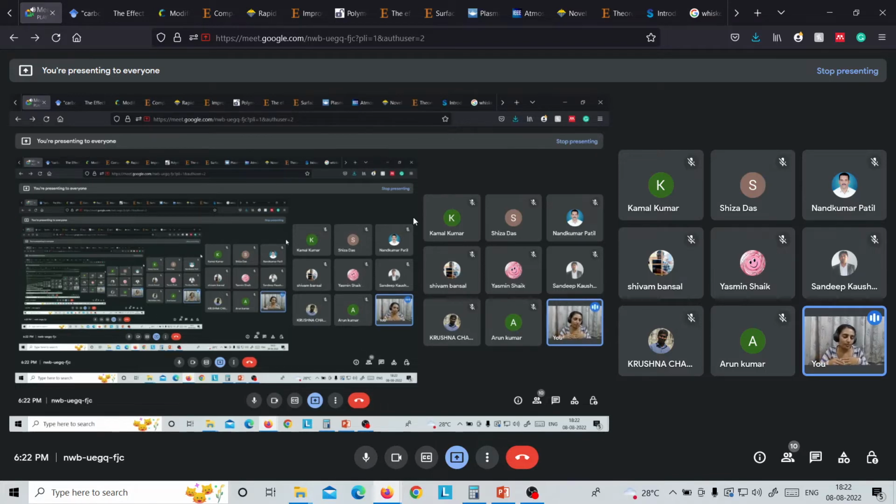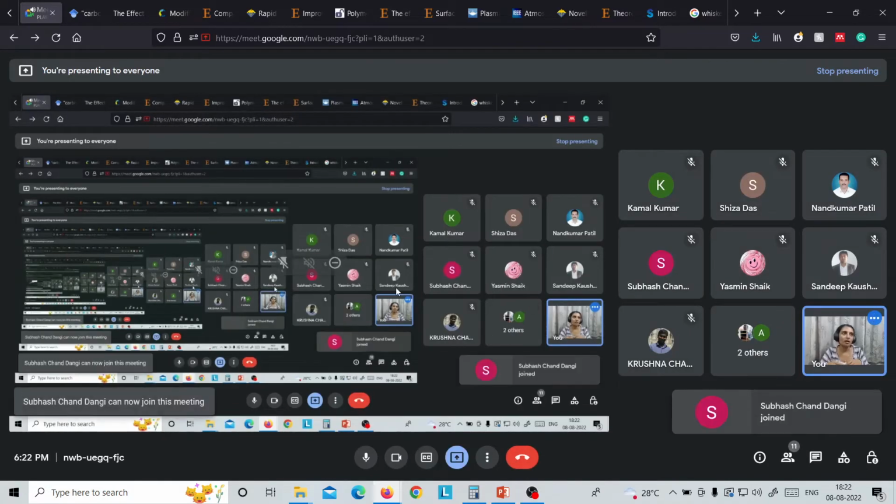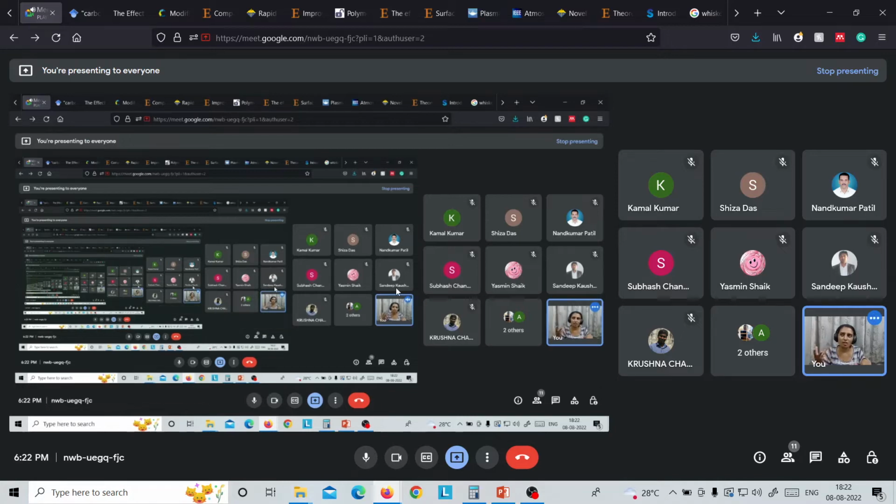Glass fibers are comparatively heavier, with a density around 2.56, while the other fibers are around 1.8. That's why glass fibers are the cheapest and most commonly used fibers, and their degradation or melting temperature is 600 degrees Celsius. But for Kevlar and carbon fiber, it's only 400 degrees Celsius or sometimes even lower, even 300. So when we compare carbon fiber, aramid fiber, and glass fiber, glass fibers can be used better for high temperature operation because they can go up to 600 instead of 400 for carbon fibers.